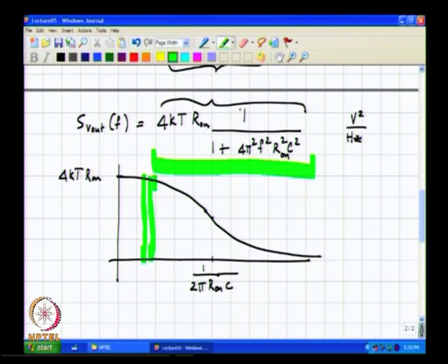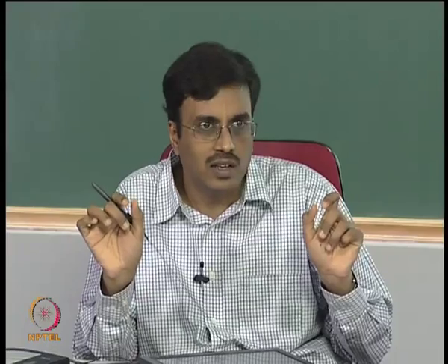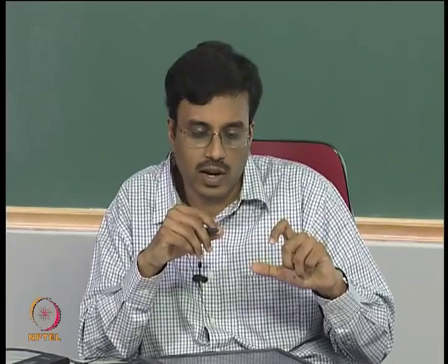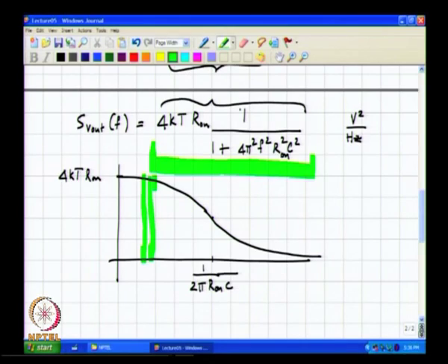So, you can think of this as a whole bunch of sine waves all separated by 1 hertz, where each sine wave's mean square value is its power. So, the mean square value of each sinusoid is this quantity here.